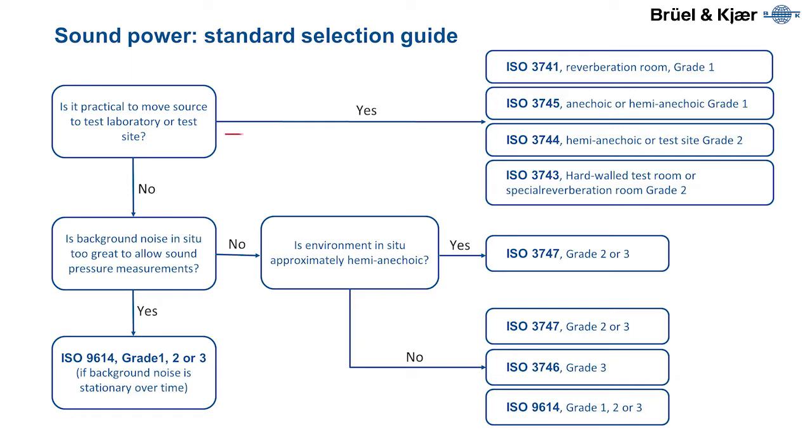Firstly, whether the device under test can be moved into a controlled laboratory environment or whether the measurement should be done in situ. Secondly, what is the type of sound field in the measurement environment? The diagram here shows the decision workflow for selecting the correct sound power standard.